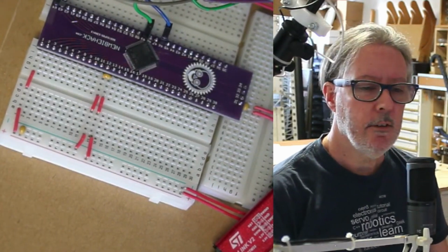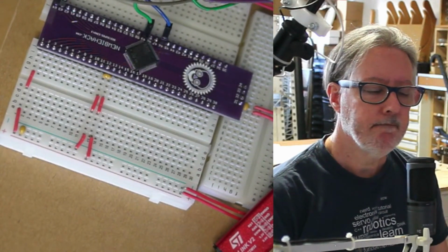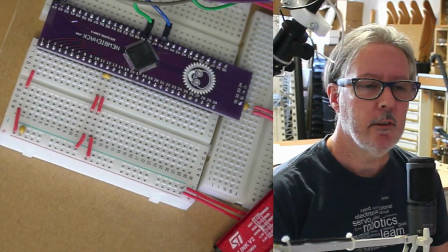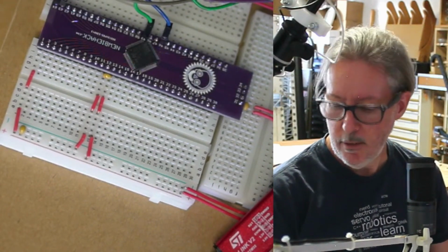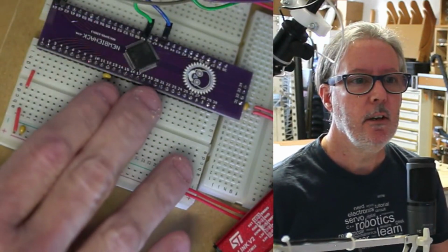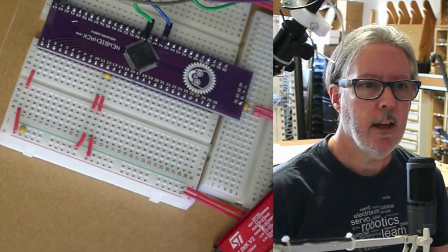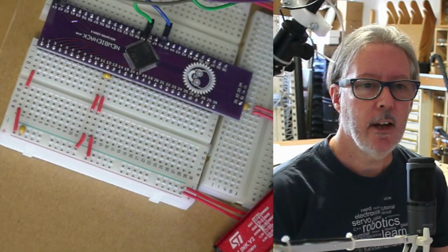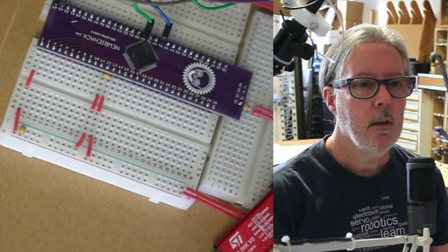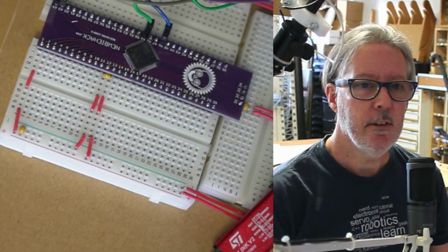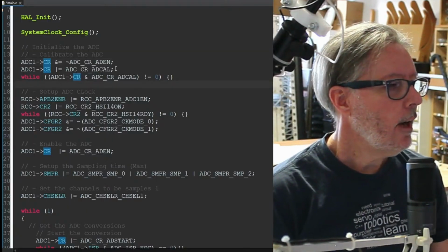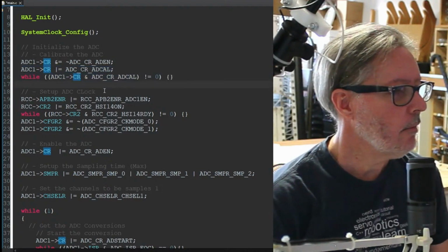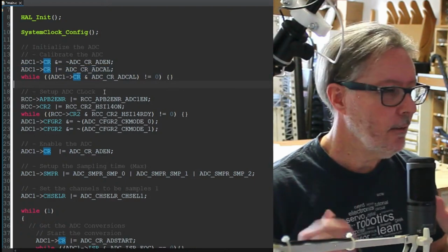And the reference voltage, according to the reference manual, is a band gap reference voltage, which means that it's extremely accurate and it's a stable voltage. So internally with the chip, they have circuitry in the chip, or designed the chip, so that the reference voltage is very stable. All right, so I'm really kind of going through this myself in my head, and hopefully it helps you guys, just so I can sort of orient myself with programming.